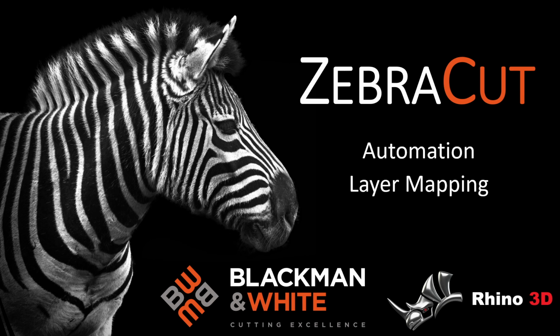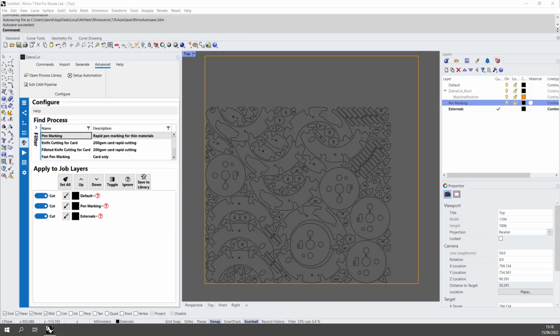In this video, we're going to explore automatic layer mapping within ZebraCut. I have here a cut file which has a pen marking and an externals layer. And what I'd like to do is to automatically assign pen marking and knife cutting to these two layers respectively.